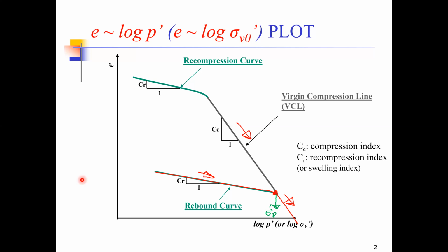So first of all, let me just start it once again for clarification. We were here at this point, we apply 100 kilopascals of load on the soil. And when we apply 100 kilopascals, there was, let's suppose, 10 millimeters of settlement. Then you unloaded the soil, you removed that 100 kilopascals, and when you removed it, the recovery or the expansion in the soil was only 3 millimeters.